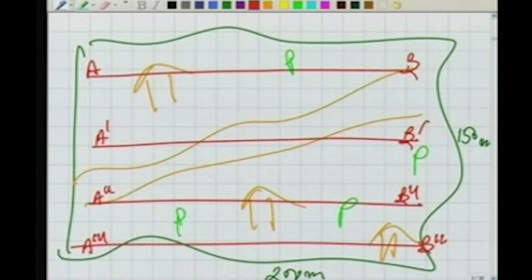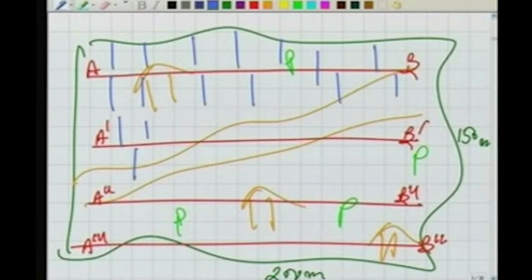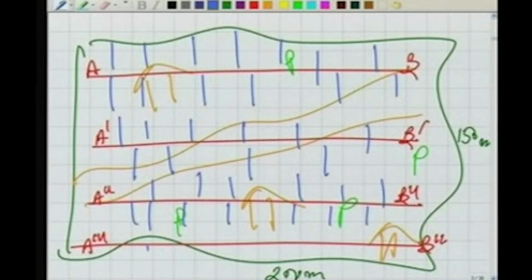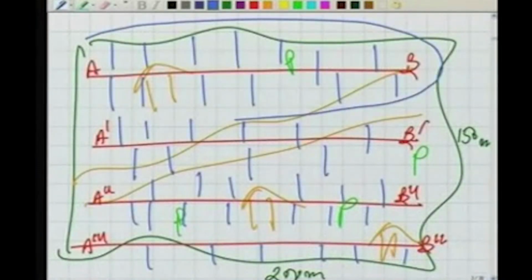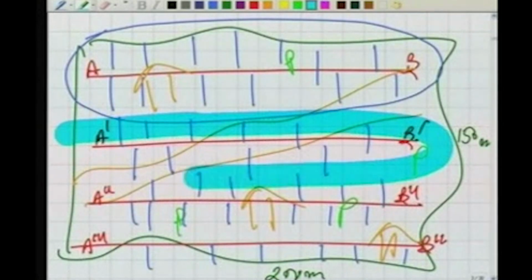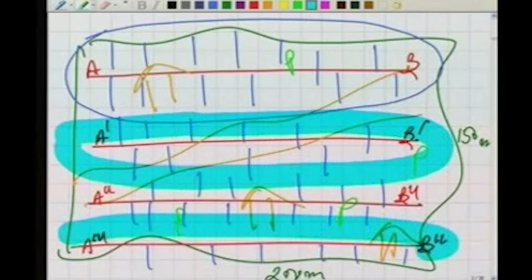Now, by taking these chain lines, what we have done, we have reduced the problem of taking the offsets. Now our offsets are smaller. I can take the offsets about this line just in its nearby area, and here also I can take the offsets. Okay, no problem as far as taking the offsets is concerned. We can take all these offsets but will it serve the purpose? Start thinking. You have noted down this entire thing in your field book. Similarly, here also, this entire thing is in your field book. Here also, all these observations are in your field book.